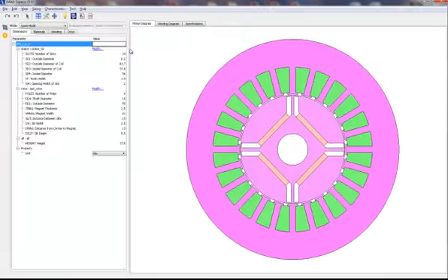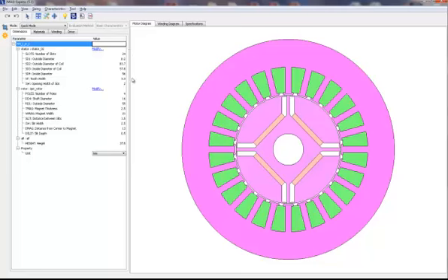If I select that first geometry, which is our most basic study, we can see that the actual model is going to open up. In this model, I can now change the geometric properties. So I can change the number of slots, outside diameter, inside diameter, and even the rotor properties. If I wanted to add certain features such as perhaps a fillet or one of these back iron teeth, or modify the geometry of the magnet slightly, I can click on this Modify button, which is going to open up the DXF geometry file, which I can then go through and modify. At this point, I won't get into that detail of an analysis yet, but the geometries are fully modifiable in JMAG-Express.